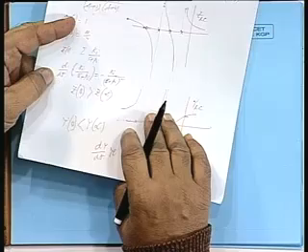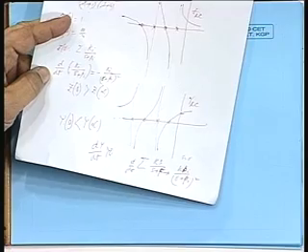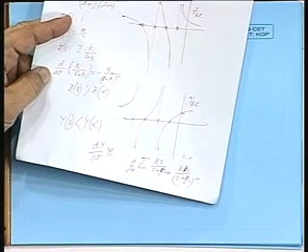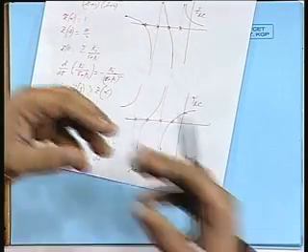Yes, please. Any question? Weaken the pole so much that the zeros become poles. Well, zeros become poles means zeros will be merging with a pole and they will vanish. So that is a total removal. That's what you precisely do. When you take out that pole totally, there is no trace of that pole in the remaining part. So it is like a positive charge and negative charge. When they join together, that becomes neutral. So when the zero merges with the pole, means the pole is totally removed.